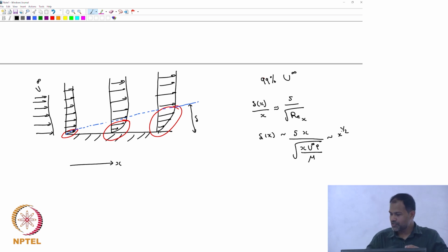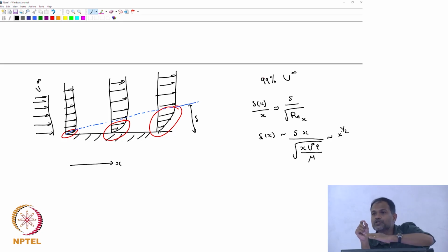As we said, as soon as the fluid touches the leading edge, only that fluid particle that is touching the leading edge will experience the effect of the solid plate. Now, what is the problem with the guy who is just behind you? Only the fluid particle that is touching the leading edge will get retarded. Everywhere else, it's still coming with that velocity of u infinity, right? But as it enters a little bit more, two of the layers will start experiencing it.